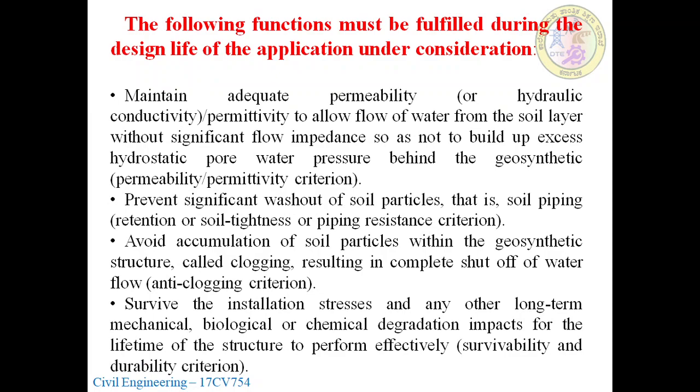The following functions must be fulfilled during the design life of the application under consideration. Maintain adequate permeability, permittivity, to allow flow of water from the soil layer without significant flow impedance, so as not to build up excess hydrostatic pore water pressure behind the geosynthetic. We will study permeability in detail in the next session.